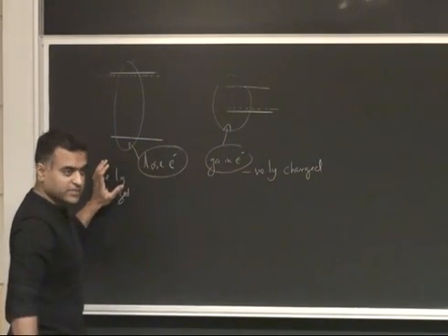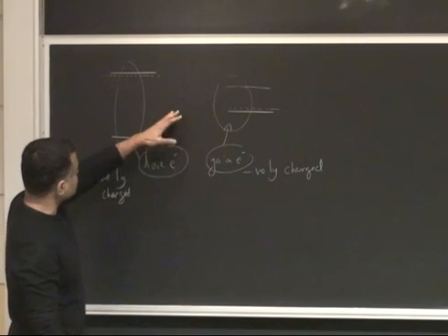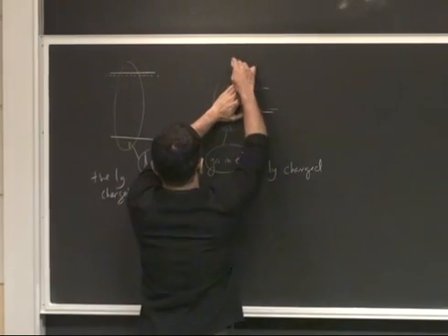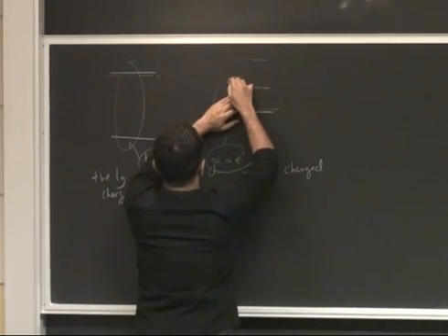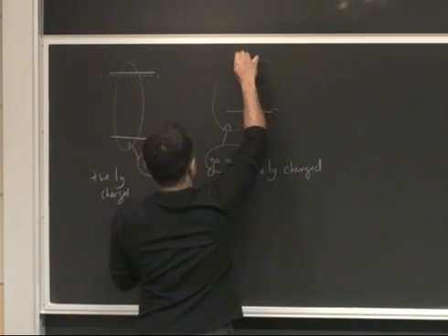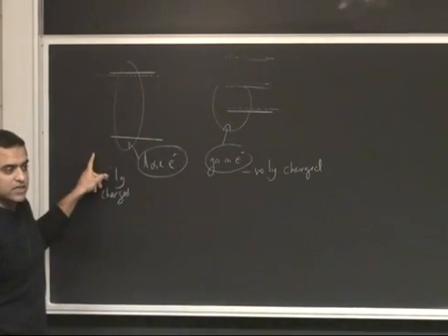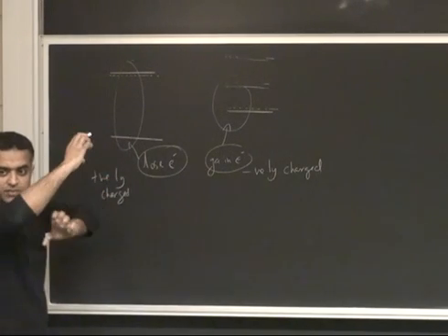It's the same thing, except here you can have a situation where the band alignment is such that the Fermi level of the p-type layer is actually higher than on the n side. It's possible, right? You can choose a broken gap heterojunction.